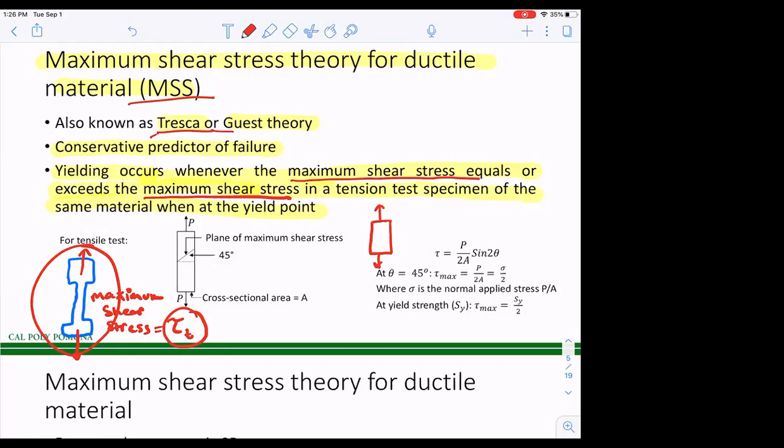Jack, I didn't hear. Transverse loading. Sorry? Tensile. Axial loading. Tensile axial loading, yes. It's uniaxial tensile loading, right? Uniaxial means you're only applying load along one axis, okay? So it's uniaxial tensile loading, okay? That's what you do in your tensile test, right?